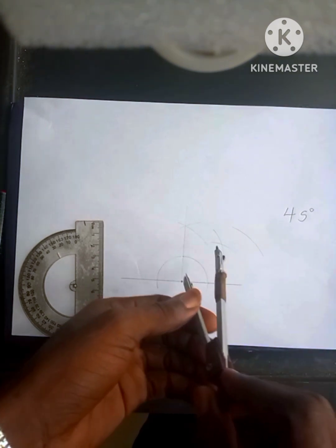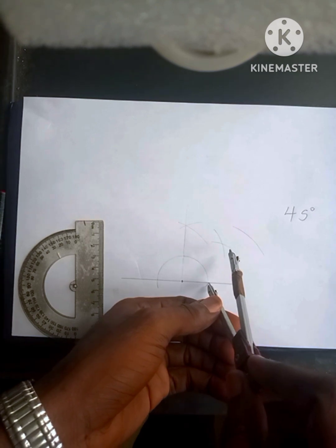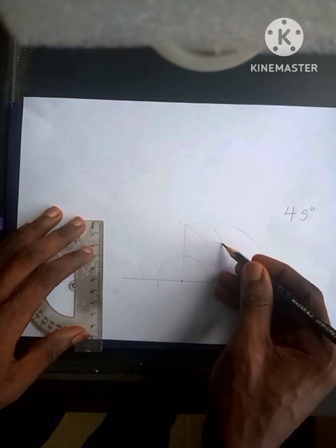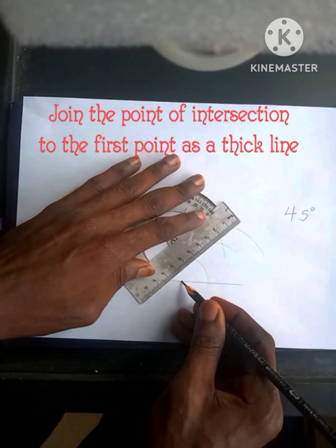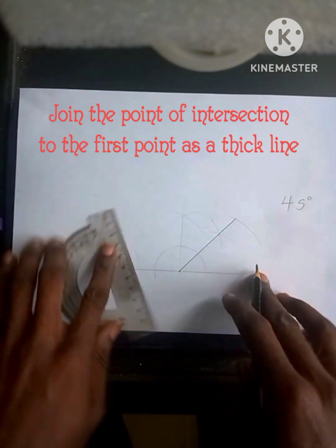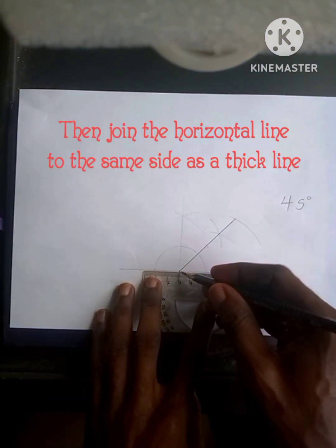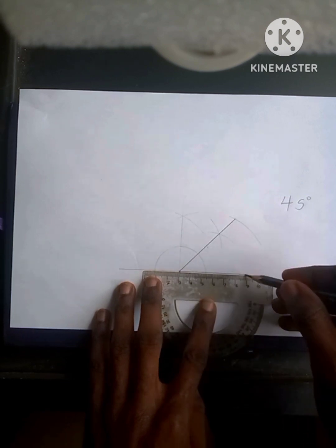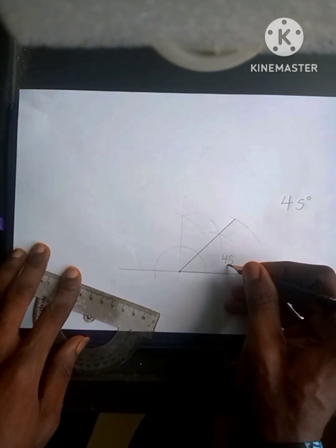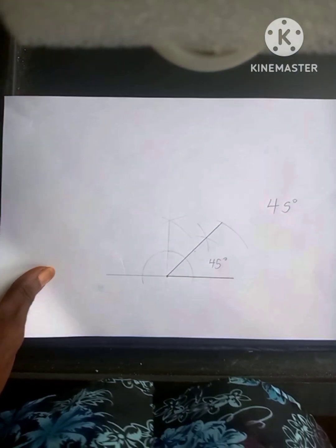Put it at the two points of intersection, both for the 90 and the point where the semicircle meets, to get an arc outward. Mark out the points, then join it to the first point that you marked out. That's the line for 45. Then join the horizontal line to the right. So that acute angle gives you an angle of 45 degrees. That's the construction of 45 degrees with a compass.